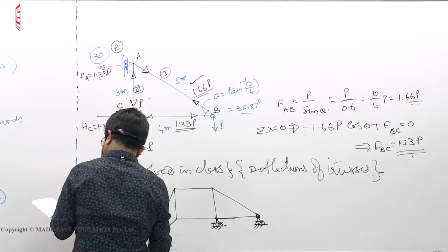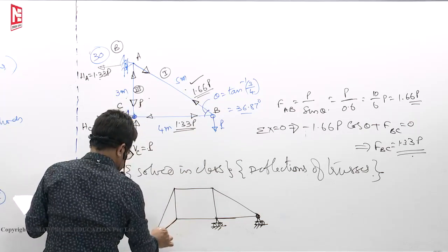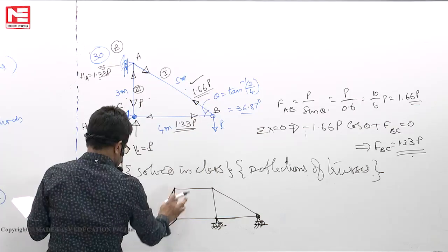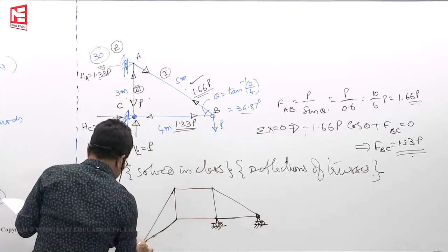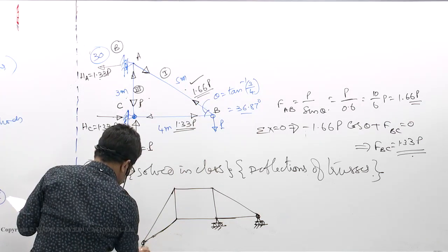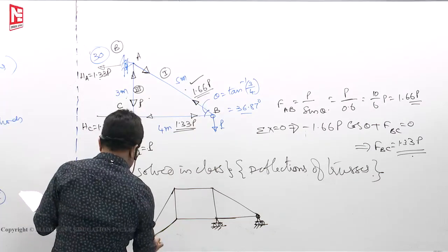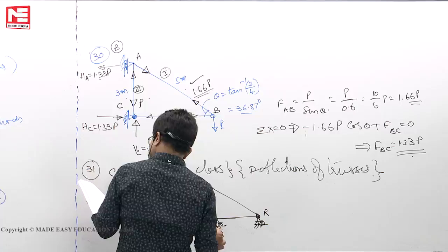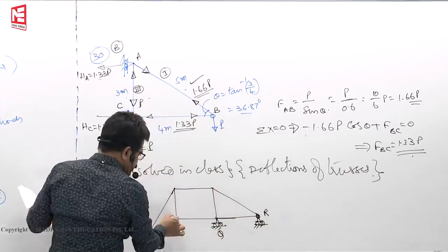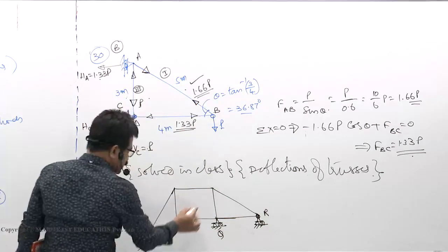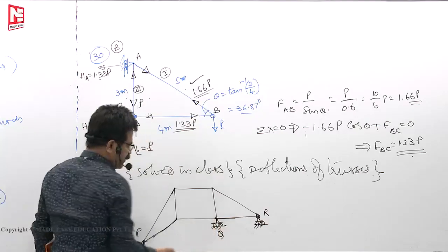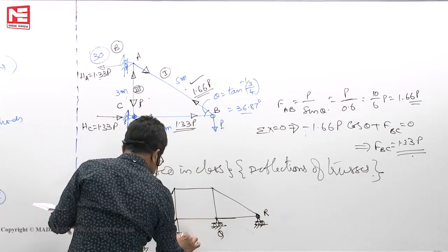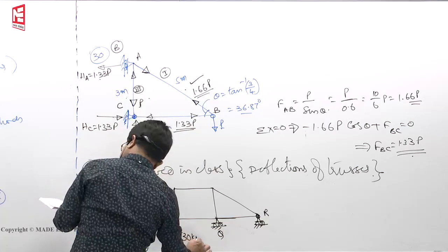This is how it is running. Okay, there is a hinge support. P, Q, R. Okay, actually there is one member missing, but that is compensated by one additional vertical reaction at Q. So it is stable. This is 30 kilonewton down.